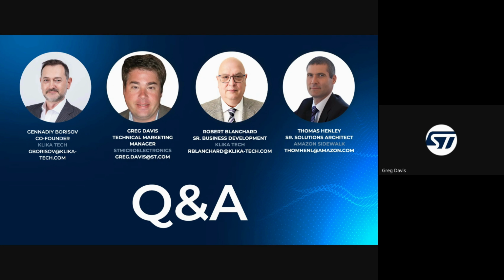So we had a couple of questions that came to us earlier. One of them was, does the ST Sidewalk SDK support both BLE and LoRa FSK concurrently while inside an active Sidewalk connection? It absolutely does. We have very robust concurrency right out of the SDK. Whether you're doing BLE plus FSK or LoRa plus BLE, the concurrency operation is extremely robust, and it even does so while entering and exiting ultra low power mode.